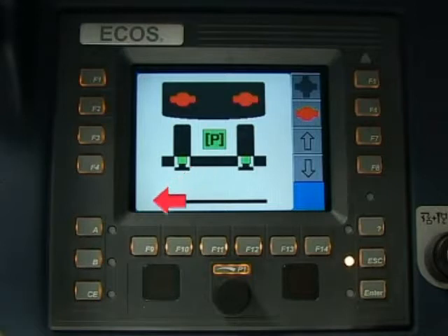The LED on button A and the warning triangle will flash when the cylinders are locked until the required pre-charge pressure is reached. We will now install and then remove the counterweight.